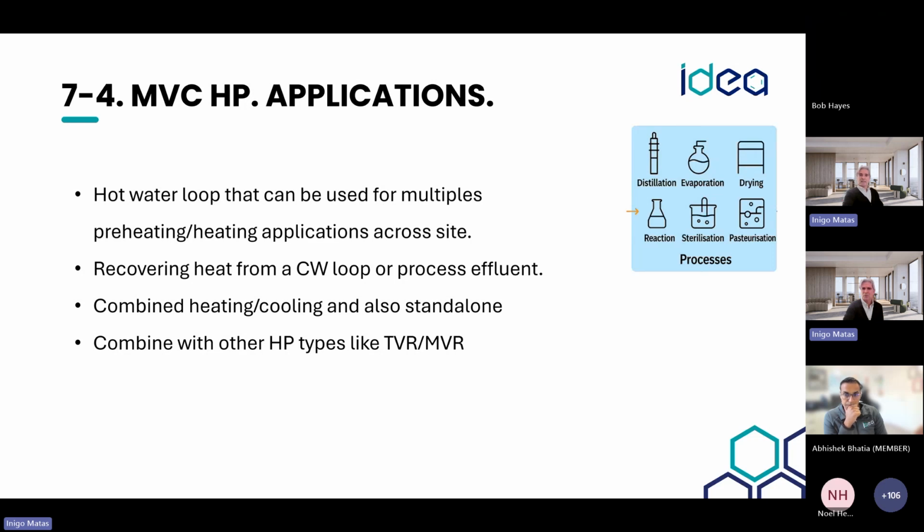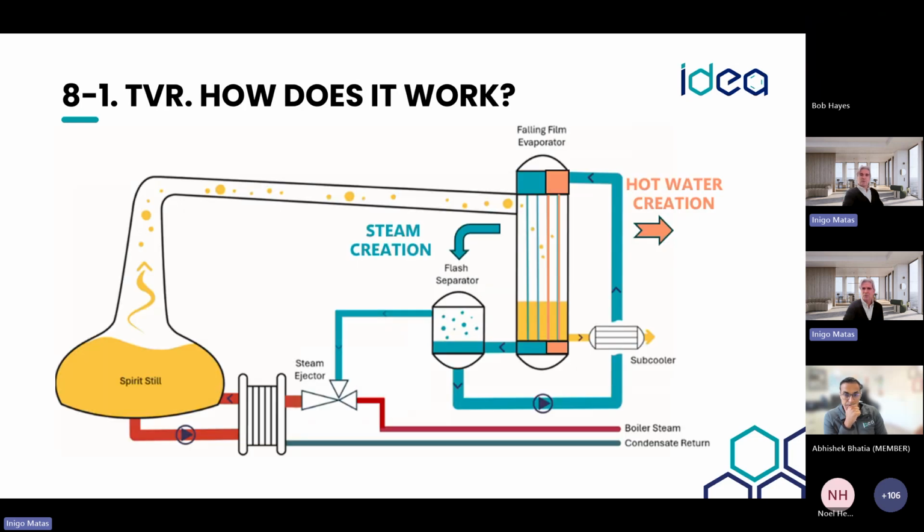Okay. The next one we move to is a TVR. So TVR is a very different system. We say thermal vapor recompression. For example, this is quite widely used in the spirit sector. So what we are doing in this case, we have some vapors arriving to a condenser. In the past, traditionally this would be removed by using cooling water.